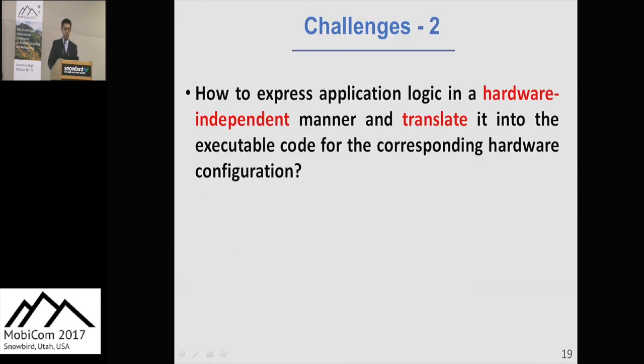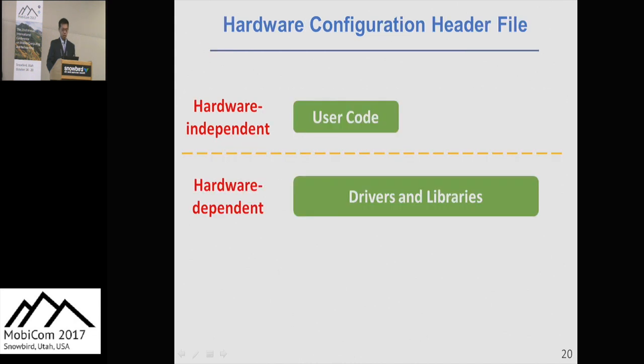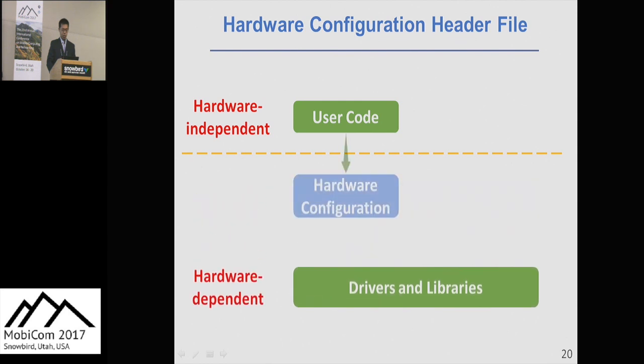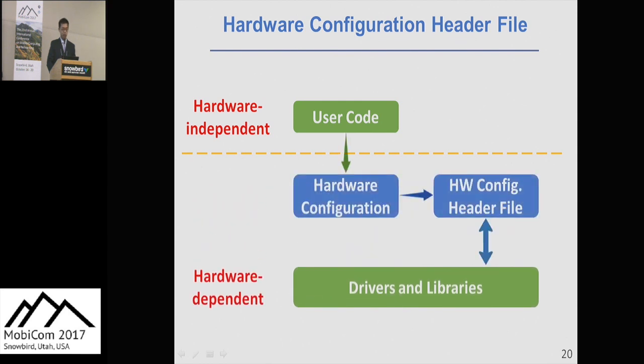Now, there is a challenge to implement the software system, that is how to express the application logic in a hardware-independent manner and translate the hardware-independent code into hardware-dependent executable code. In order to fill the gap between the user code and the drivers and libraries, we utilize the hardware configuration to generate the hardware configuration header file, which uses macros to solve this problem.